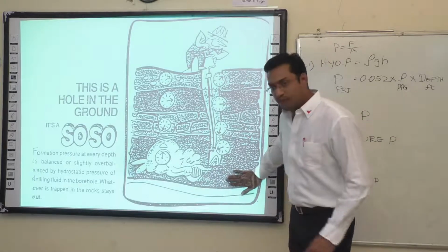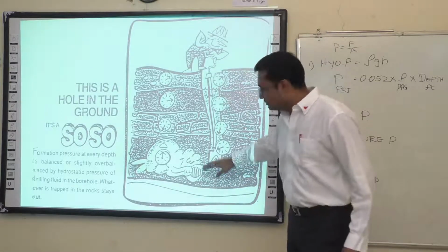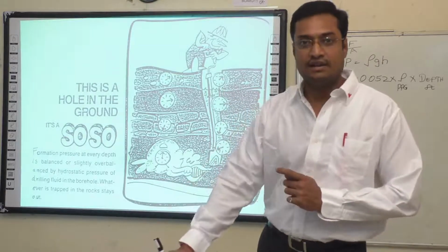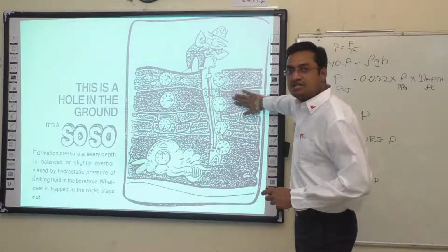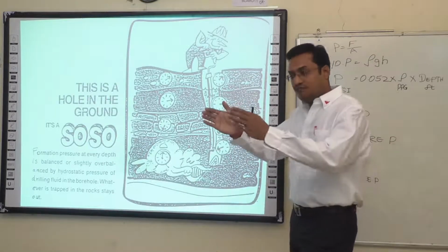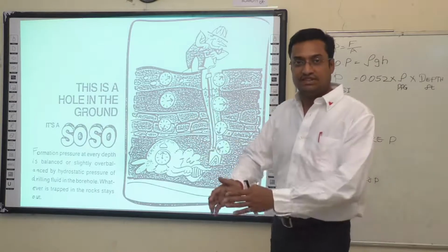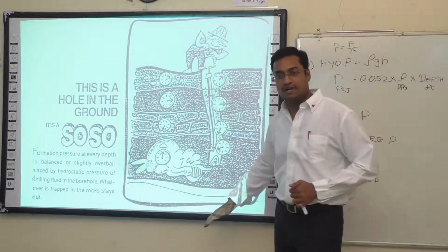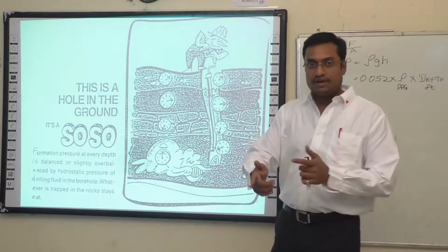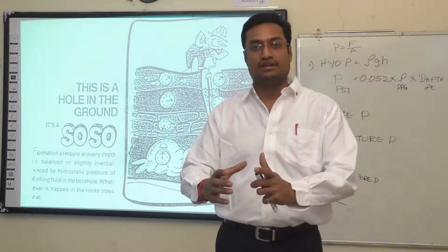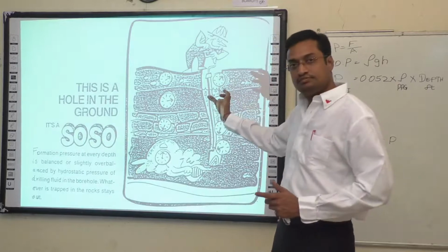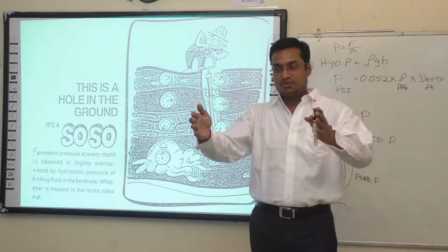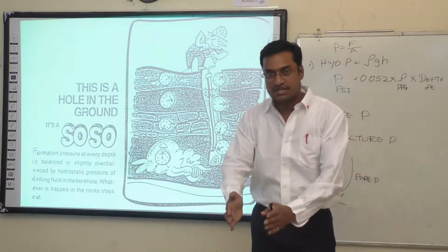This is the formation that we are going to drill at the surface. Drilling is nothing but making a hole in the ground. As we go deeper and deeper, we make sure the formations which we have drilled are safe, so they are not going to affect us in further drilling. So we run casings at every level as we go deeper. As we start drilling deeper, the hole size starts reducing, so it becomes like a telescope. We start with a larger diameter. Once we run a casing, the next drilling is going to be a smaller size. Casing, next smaller size, and casing.